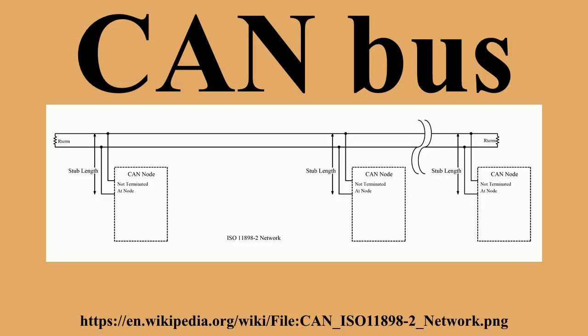First, the RTR bit is transmitted as a dominant bit in the data frame, and secondly, in the remote frame there is no data field, i.e. RTR equals 0, dominant in data frame. RTR equals 1, recessive in remote frame. In the event of a data frame and a remote frame with the same identifier being transmitted at the same time, the data frame wins arbitration due to the dominant RTR bit following the identifier.